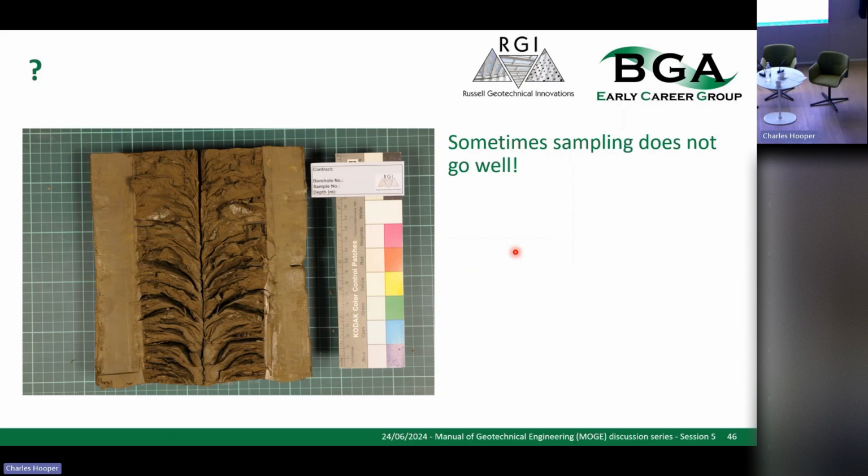But clearly what has happened here is that they weren't actually rotary coring. They were, unfortunately, without knowledge, just pushing the core barrel down into the sample, and it has completely destroyed this material. So getting good parameters for design out of this material, I would say, no, you're not. It's not going to happen.